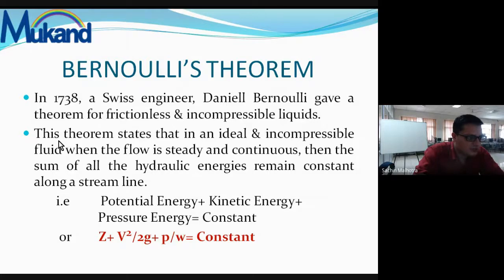According to this theorem, what does it state? This theorem states that in an ideal and incompressible fluid, when the flow is steady and continuous, the sum of all the hydraulic energies remains constant along a streamline. Now, in the previous slide we have already studied the types of hydraulic energy. So what are the types of hydraulic energy? Potential energy, kinetic energy and pressure energy.